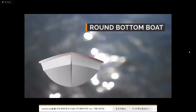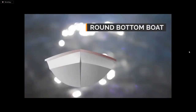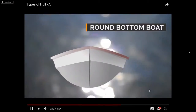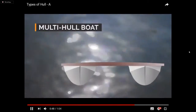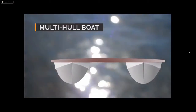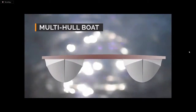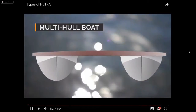Round bottom boat. It moves easily through the water, especially at slow speeds, but tends to roll unless fitted with a deep keel or stabilizers. Many trawlers, canoes, and sailboats have round bottoms. Multi-hull boat. Catamarans, trimarans, pontoon boats, and some houseboats have a multi-hull design. The wide stance gives greater stability. Each of the hulls may have any of the bottom designs described above.